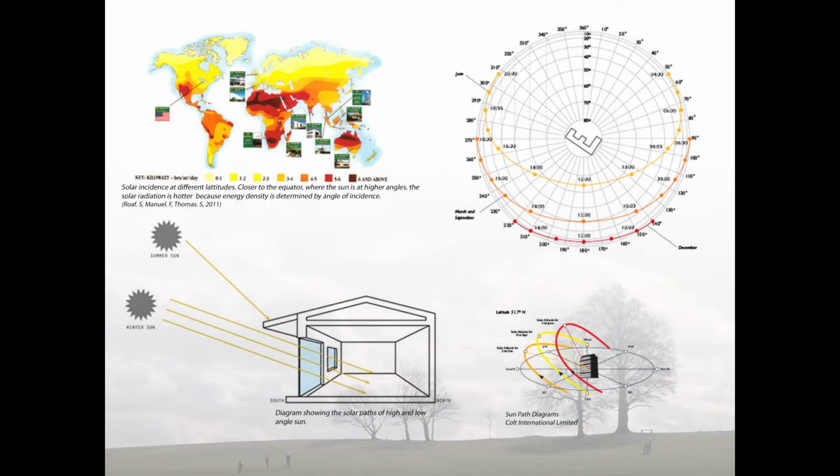The main principle in selecting the correct solar shading device is orientation. Orientation lets you choose the device and what type it is in terms of which wall it will be applied on. In the summer and at lower latitude countries, the sun has a high solar angle, whereas in the winter and early morning and evenings, the sun is at a lower solar angle. Understanding the position of the sun in relation with building orientation, seasons and time of day is crucial for optimizing the performance of solar shading devices.